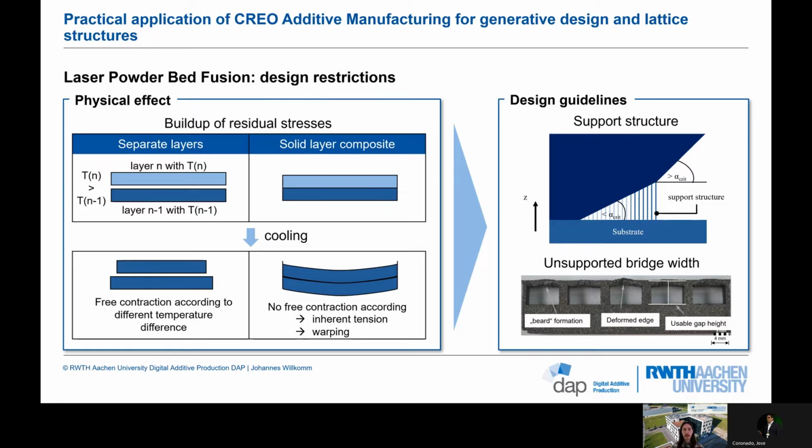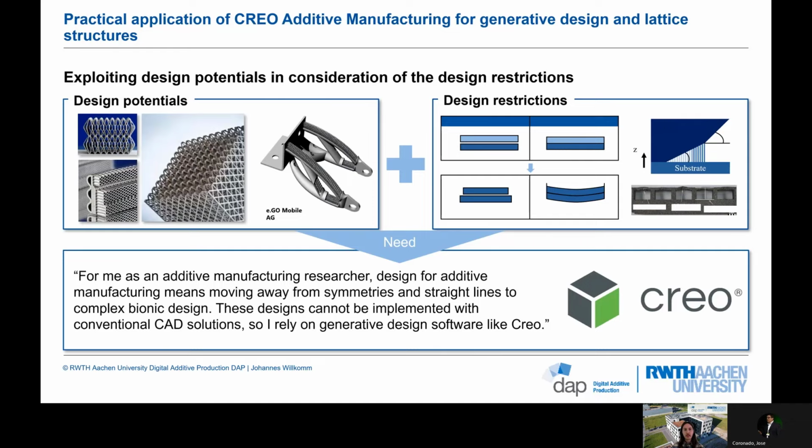So we have on the one hand the design potentials of laser powder bed fusion, for example internal complex structures and lattice structures, but on the other hand there are big design restrictions, especially support structures which have to be removed after the process.